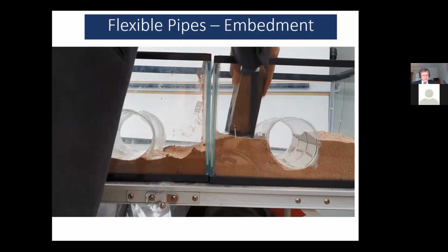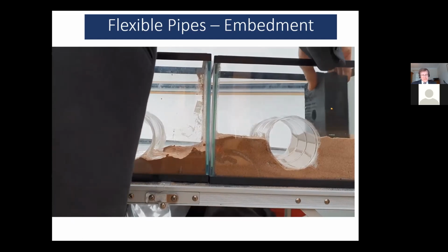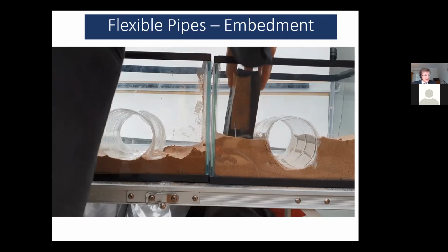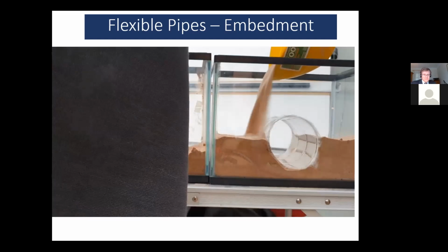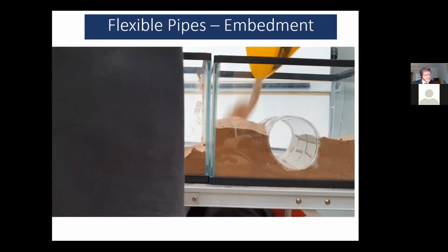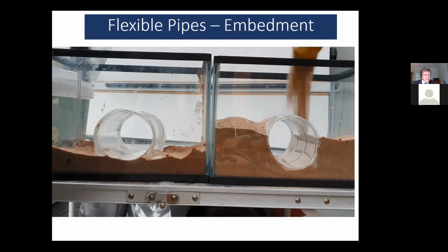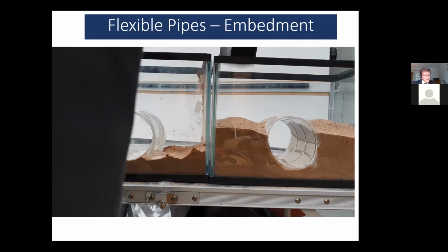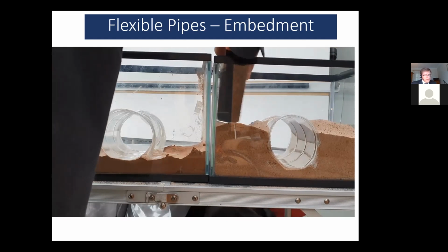And they have laboratories on sites, and they're continually doing proctor density tests and testing the materials coming in that they're going to use as backfills, and then checking that the actual compaction has compacted it to the specified density. And it's quite a thing that goes on. In the UK, we've tended to use self-compacting gravels, and so we've not had the compaction issue.